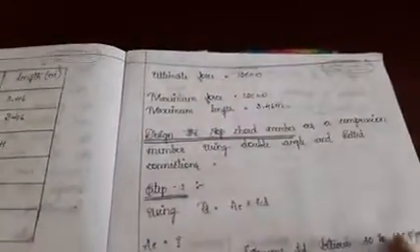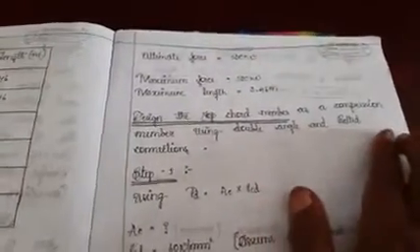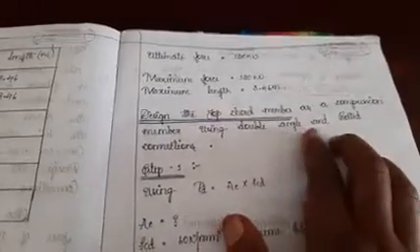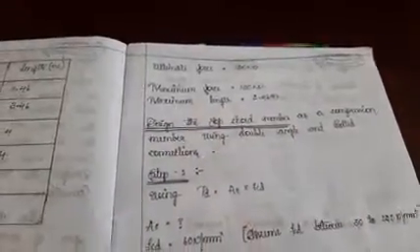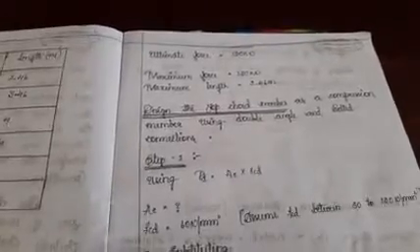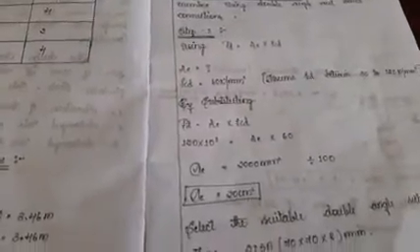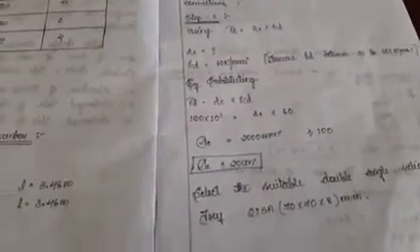As I said earlier, the sign convention was negative. So it means you need to design the top chord member as a compression member using double angle, because I told you in the earlier class that while selecting an angle for the bottom chord as well as the top chord member, you need to select a double angle. And here I am doing it with bolted connections. Okay, for this step 1, we'll start with the next class. Till this, please understand this.